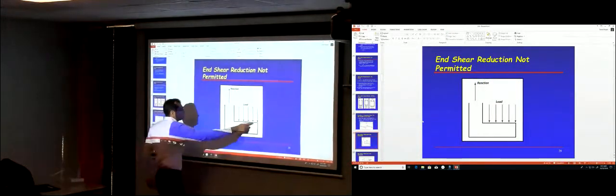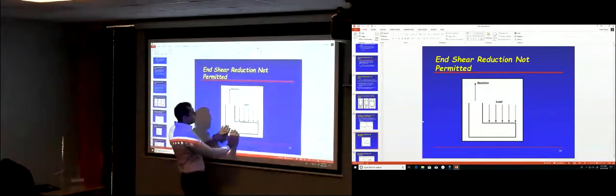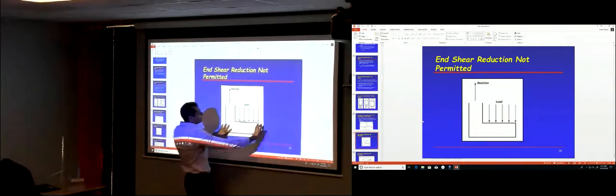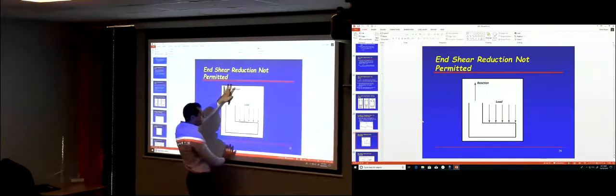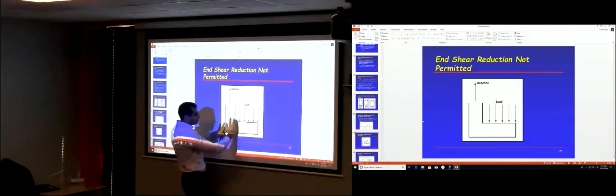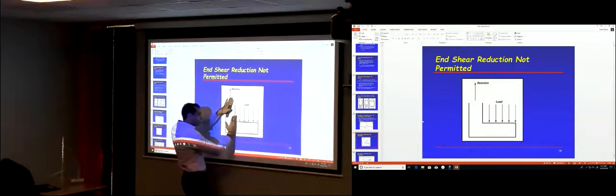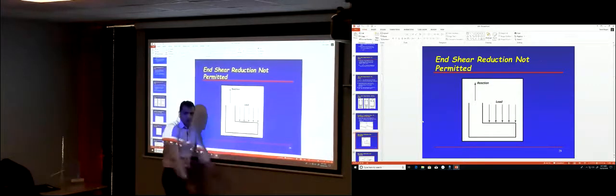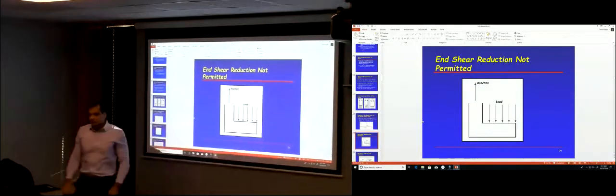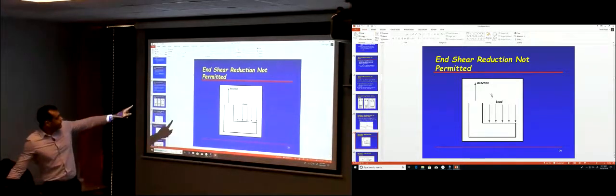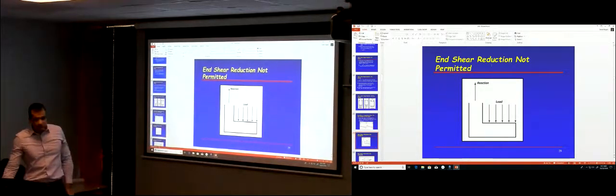something like this also. So actually the column, or the part that is supporting your beam, is on the top, okay, on the lower part, and the load is on the top. So if this part, at the distance d, no, it will still cause shear. Even the load till this point will still cause shear to your beam, okay? So this is another exception. So those are the cases where there is no reduction permitted, okay?